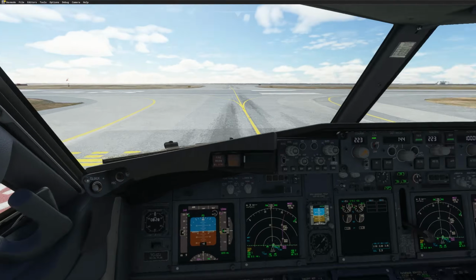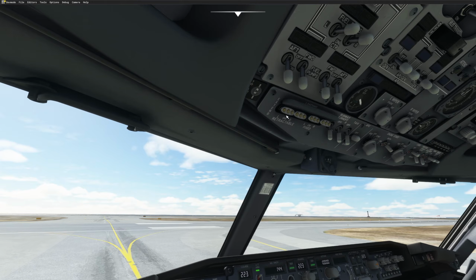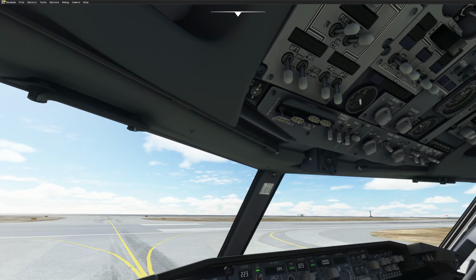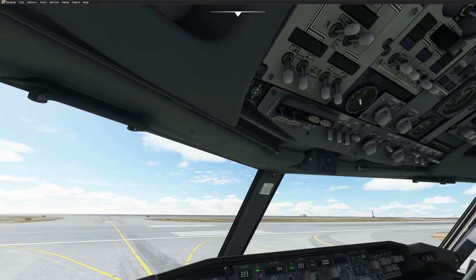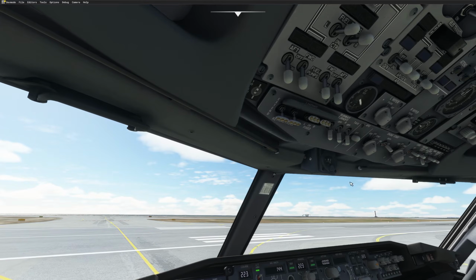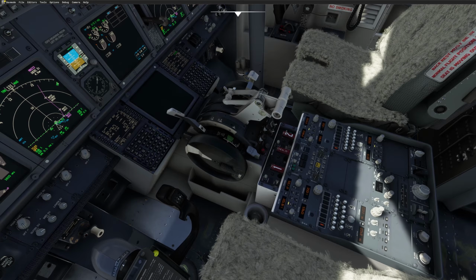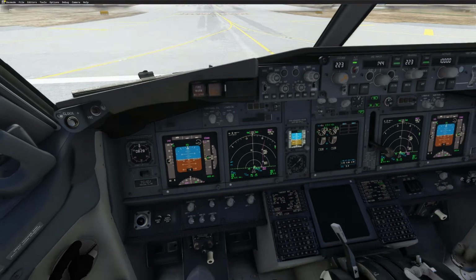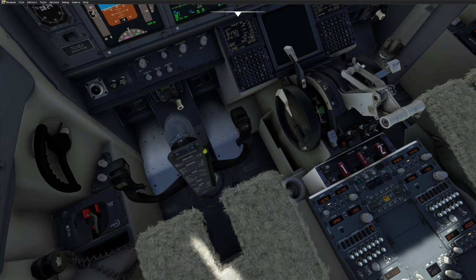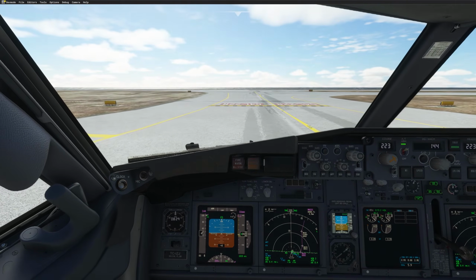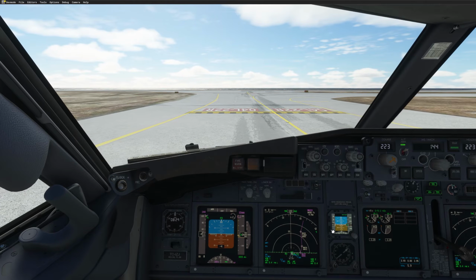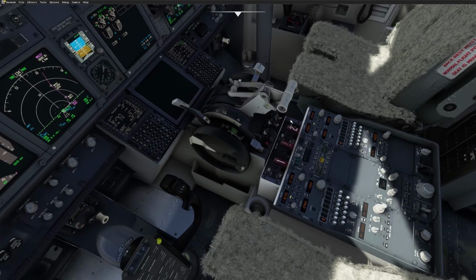I can see no aircraft on final, good, and we will set the lights. So we are not clear for takeoff, so what I do is only the retractable, then the strobe, and we can go ahead with the transponder. 2254. I changed the frequency, sorry guys. We'll look at that later on, and I will advise the cabin. Cabin crew, takeoff in 1 minute. Perfect. Crossing the runway, we are clear to line up on the other side, and the transponder was 2254.